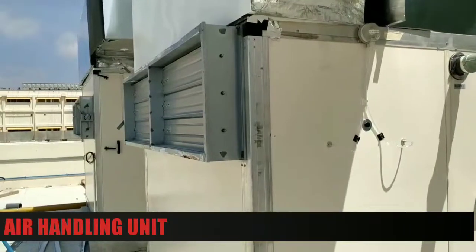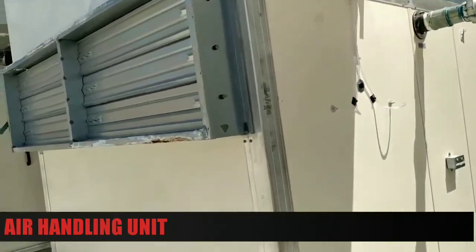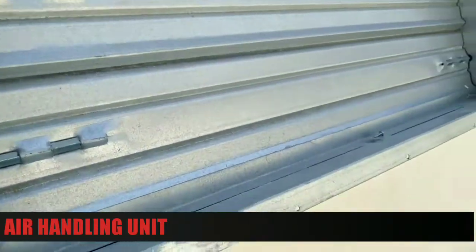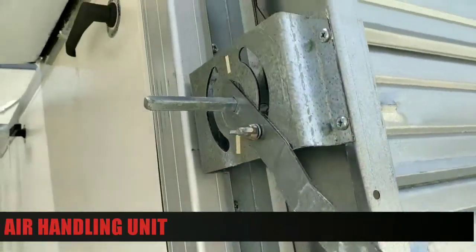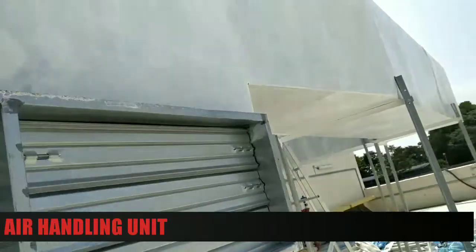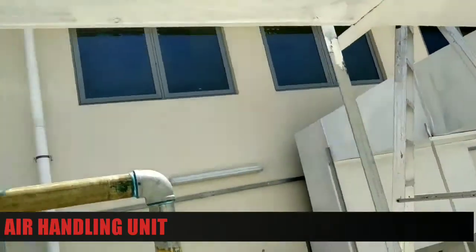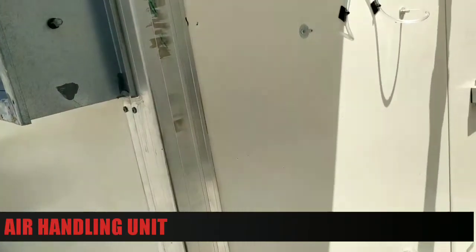Okay, this is the fresh air damper. The damper is based on the CO2, carbon dioxide. The damper will automatically open and close. Okay, so this is the return ducting from the room. From the building, return air is coming into the AHU.